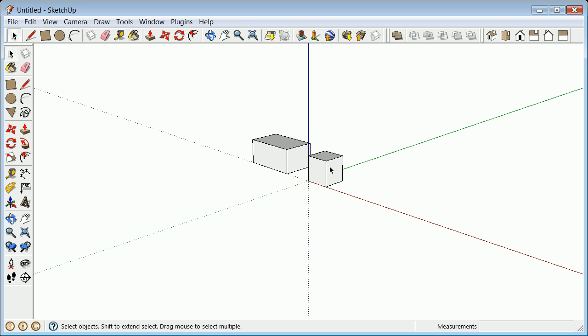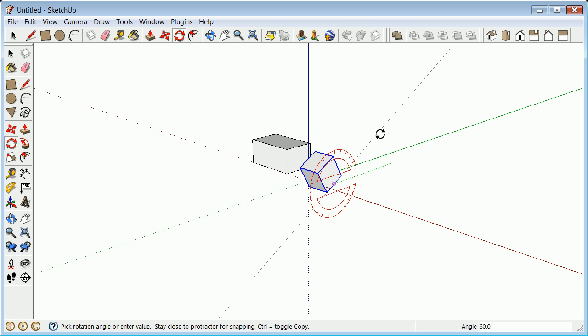Now if I want to change that group, maybe perhaps rotate it up 15 degrees or so, here's how you do it. Spacebar is select, I select, I go to my tool, this time it's rotate, I find a face that describes the plane of rotation, and I hold the shift key. Holding the shift key down, I then go to my place that I want to rotate. I'm going to hit left click, move my mouse up to start an angle, and I turn it up here, and I can then key in whatever I want. 15 degrees.